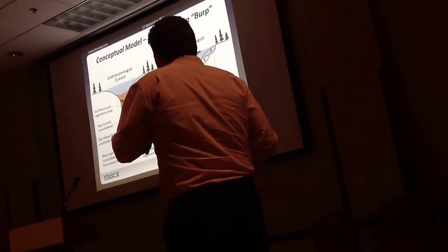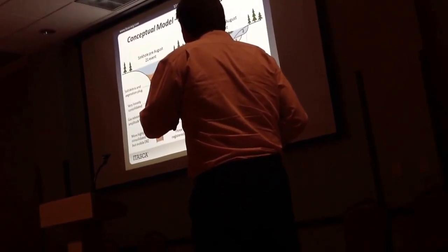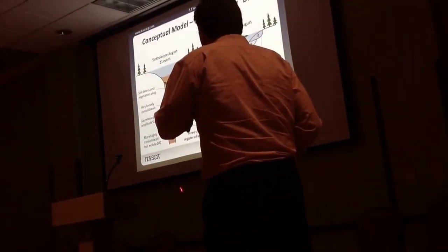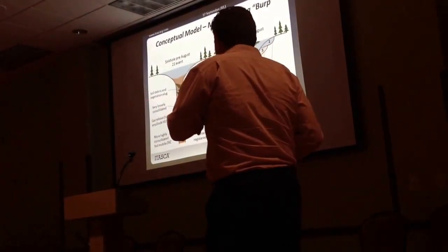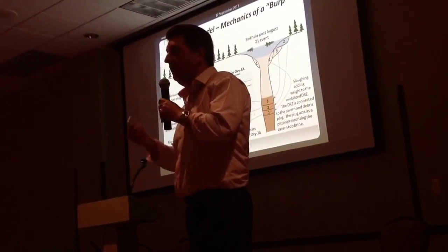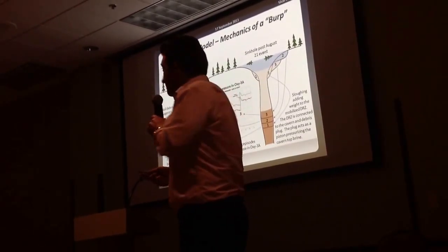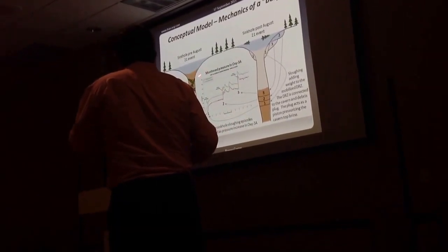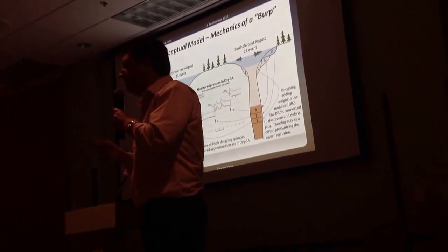This was kind of the situation before. So what we have is the sinkhole, and beneath the sinkhole we have this mud that's forming part of the disturbed rock zone that goes down to the cavern, and we also have trees that are lodged in that material as well. Coming up is gas. And this gas produces these very low period events that you might have seen on the helicorders, the seismic instruments that are out there. As it flows up, this gas actually causes a triggering of slope instability on the side of the sinkhole. And this is a very natural phenomenon.